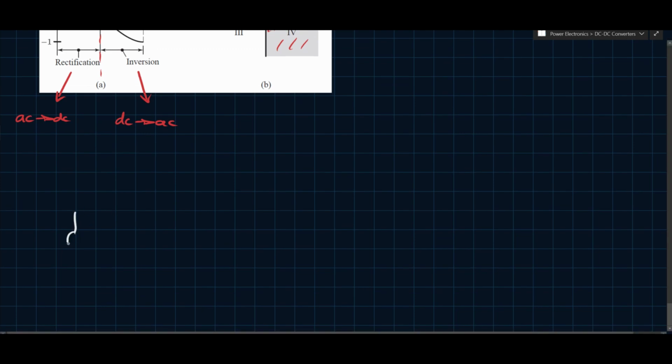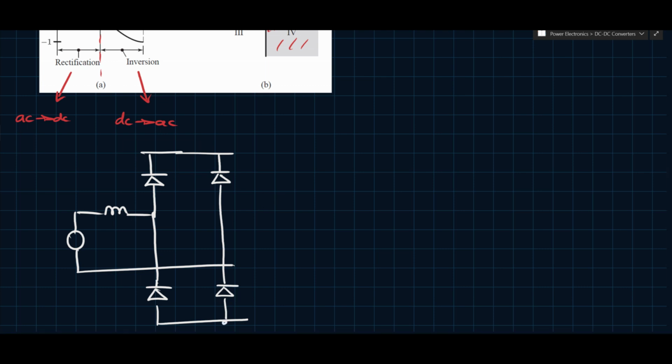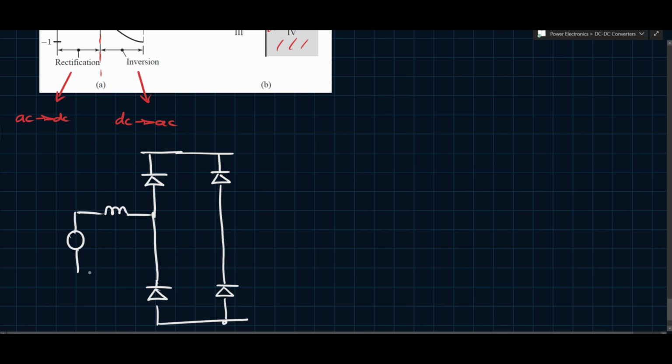So what we're going to do is have a voltage source, and there's going to be a series inductance, and this is usually something very normal and very much expected in a practical system. You expect to have some inductance, whether it's large or small is a different story, but you almost always will have some. Oh, I forgot the switch there. You will almost always have some inductance, no matter what you do, whether it's a power supply's inductance, a transmission line, or a filter of some sort, and those things will impact the operation of the circuit.